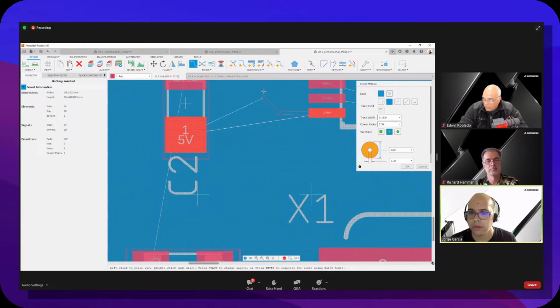Okay, a couple of other things here. You notice that it switches direction pretty fluently. If I want it to kind of snap in ortho, stay kind of in one main direction, you can hold control. And you'll see that unless I really break away, it maintains its direction. So that's also a new feature. Trying to make sure I cover as many as I can because there's a lot in the route command.